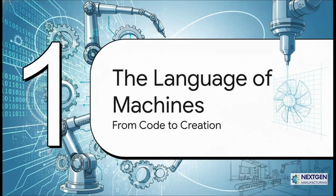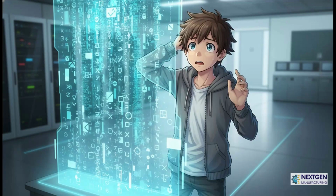Okay, so now that we know what it is, let's get into the nitty-gritty. Let's look at the grammar of this language. How on earth does a simple line of text make a giant machine perform a complex physical movement? I get it. You look at a string of G-code like this for the first time, and it can look, well, pretty intimidating, right? It just looks like a jumble of letters and numbers, but there's a logic to it. You've got a G01 command that's telling the machine, hey, cut in a straight line. Then maybe a G02 command saying, okay, now cut a curve. Once you crack the basic logic, it all starts to click into place.